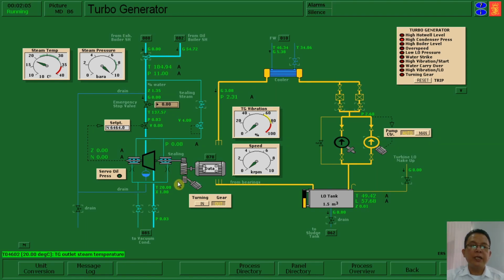Before we proceed, let us turn our engine with the turning gear, or what we call the jacking gear. Since the lubrication is already working, we can rotate the turning gear for just a couple of minutes. If we find that the engine is turning, then that's enough and it is okay.